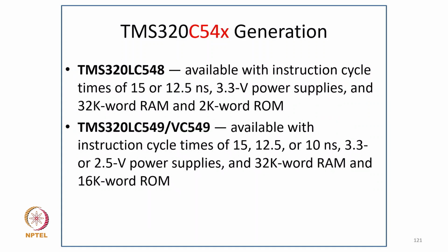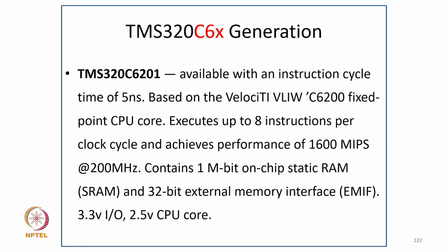So now the TMS320LC548, available with an instruction cycle time of 15 or 12.5 nanosecond, a 3.3 volt power supply, 32K words of ROM and 2K words of RAM. And TMS320LC549 or VC549, available with an instruction cycle of 15, 12.5 and 10 nanosecond, a 3.3 or 2.5 volt power supply, 32K words of ROM and 16K words of RAM.